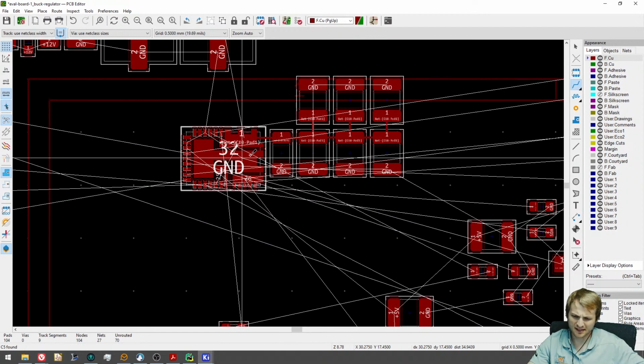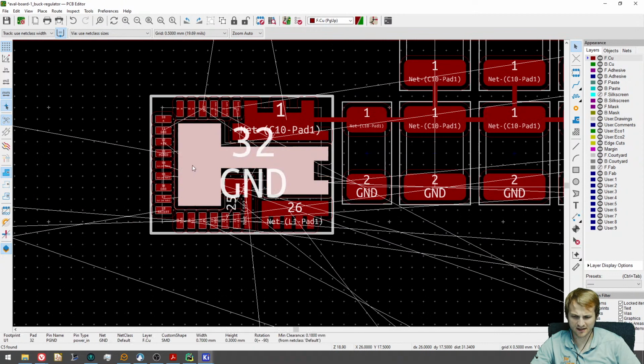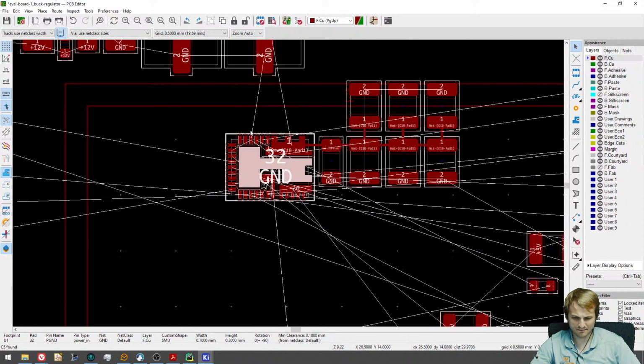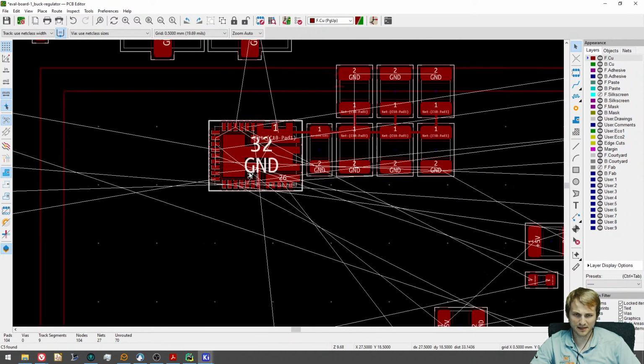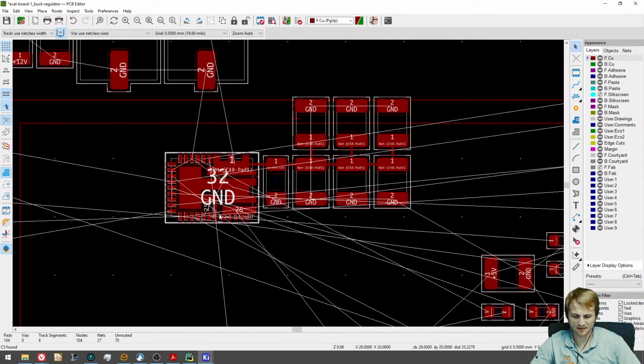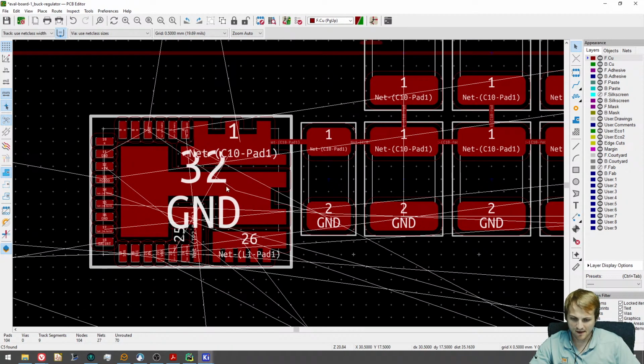On something like this, if you really needed a heat sink, you're better off tying it in on the bottom side here. On the top side, you're going through the outer shell, or the case, which is never going to be great. But even if you were, I would much rather have the caps close and just live with it being hot. I wouldn't sacrifice the caps to have a heat sink on it.